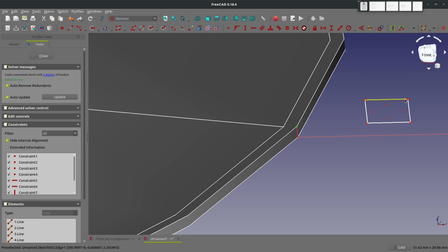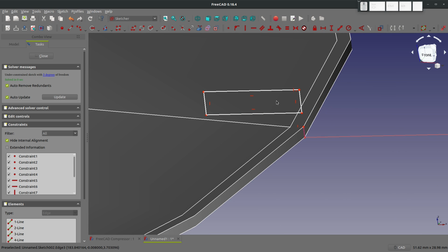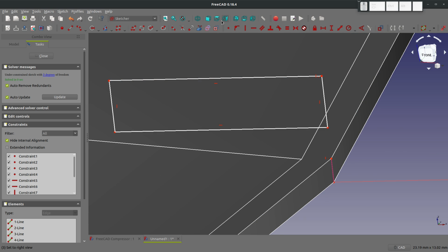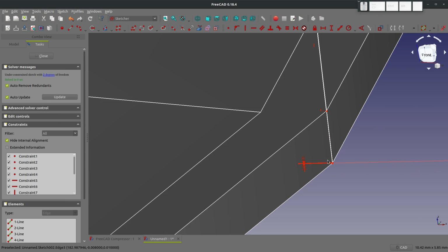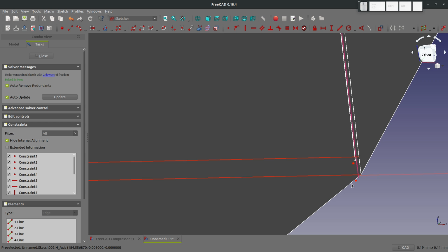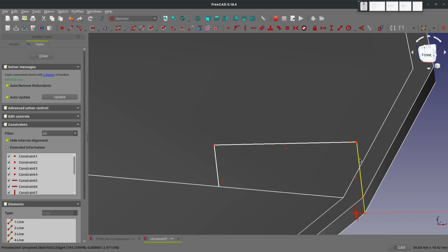And let's choose vertical. And I think the blade is going to come in as a separate body from our Revolve. And I'm going to perhaps try in vain to foresee any possible problems with fusing those together. Shift V for vertical, let's go with 0.01 millimeters, right? That's negligibly different in thickness, but it keeps the bottom of the blade from being kind of like a single point touching as we go to create the blade.